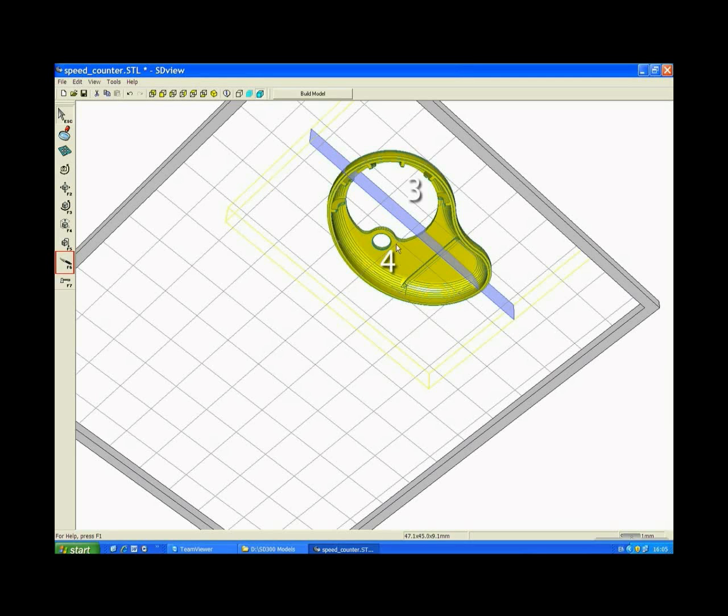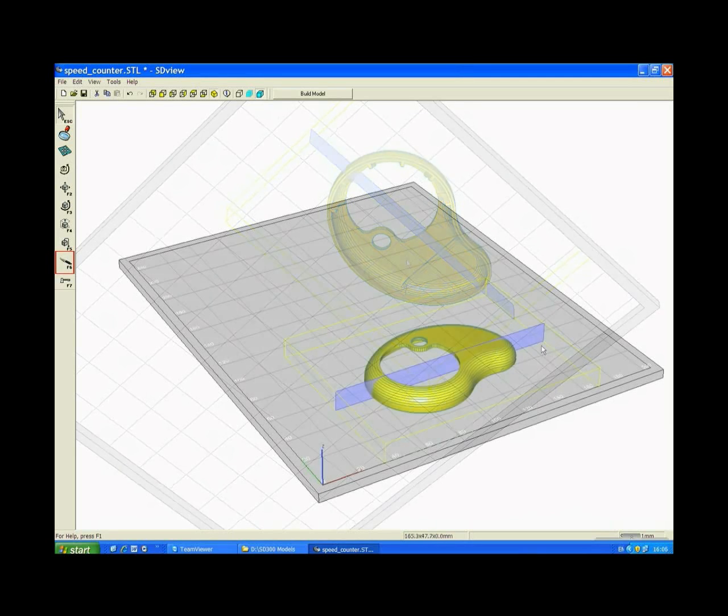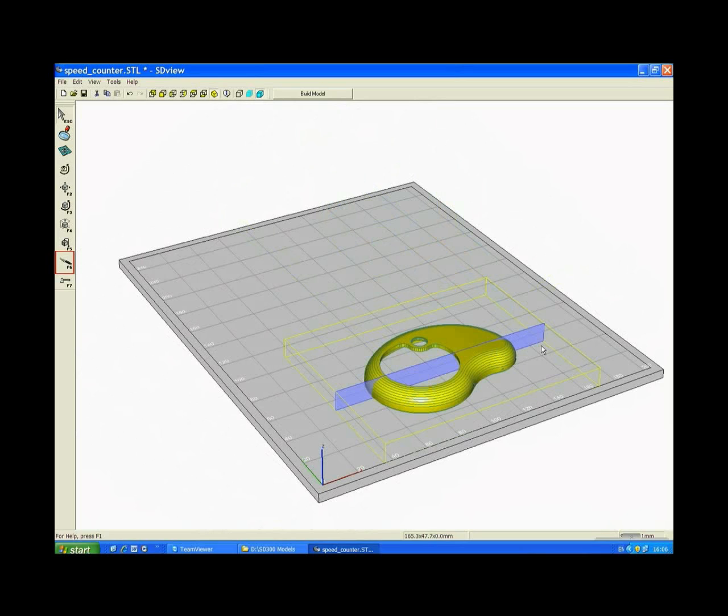2 additional sections to remove. When placing a peeling cut, one may alter the peeling cut according to need. When placing the cursor close to any one of the peeling cut edges, the edge will turn purple. When clicking the mouse button, you may select the edge and drag the peeling cut to any desired location.